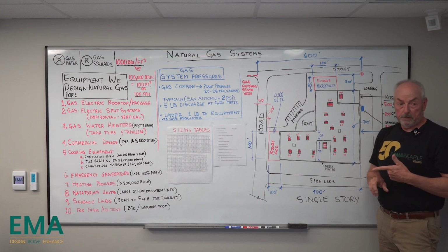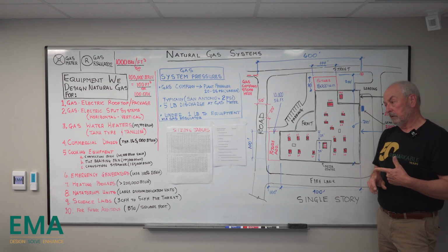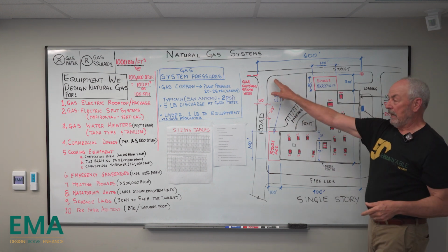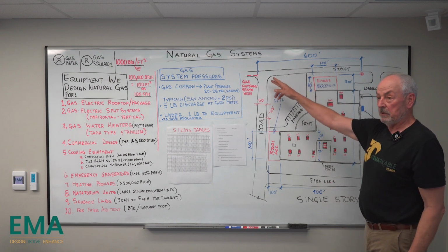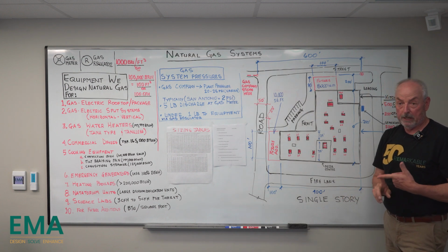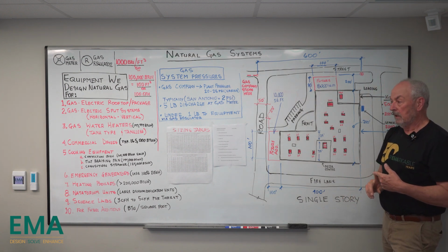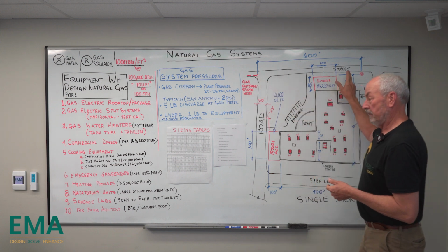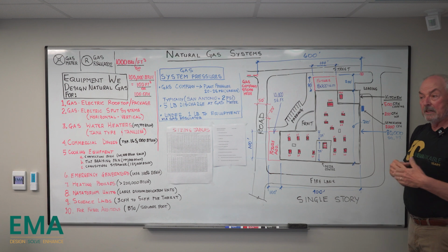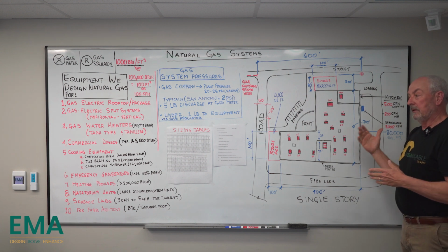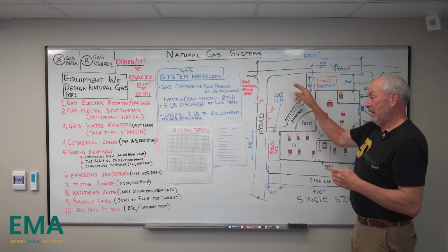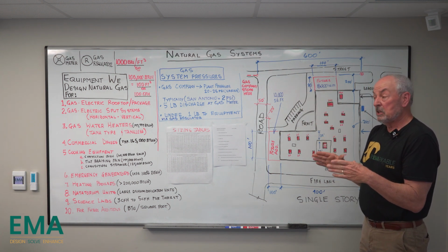Because what we don't want to happen is to get finished with the drawings and the project bid, and then the contractor starts coordinating with the gas company. All of a sudden it's $150,000 to get gas extended to the site. And right out of the gate, we've got a big change order, and the owner's going, why didn't we coordinate this? What we do is coordinate with the gas company, and then we send the information to the project manager. They send it to the architect, and then they place that amount in a general contingency fund.